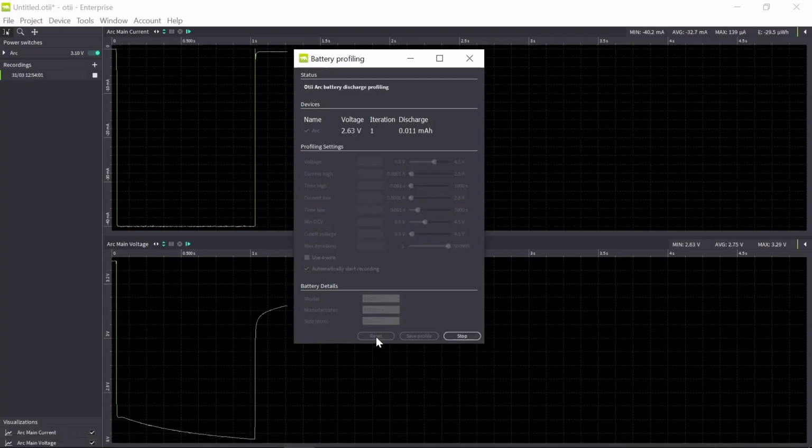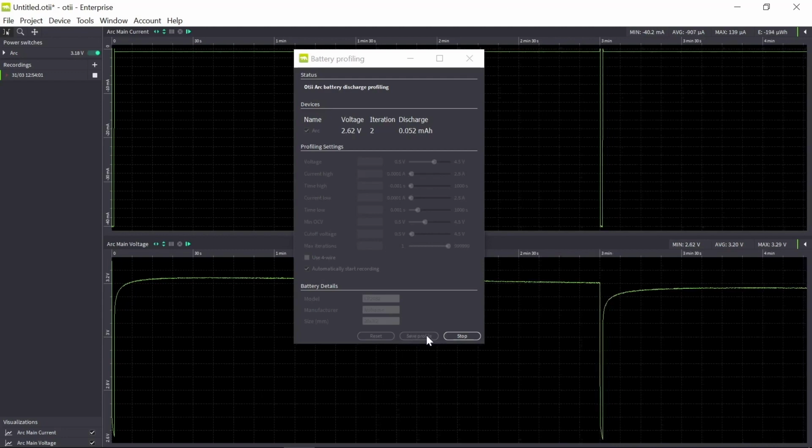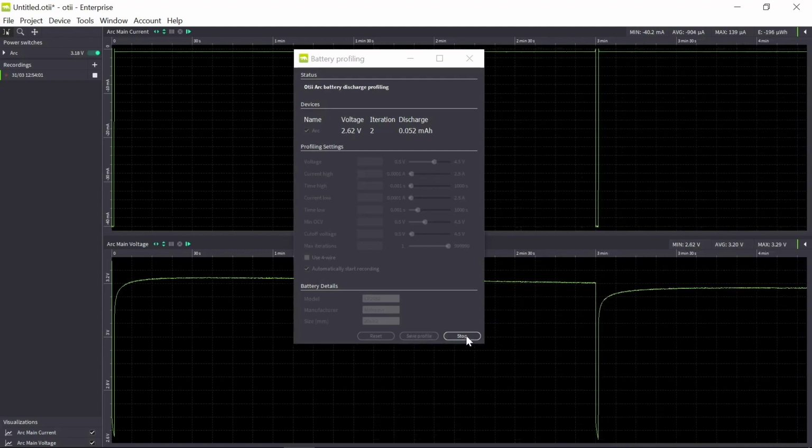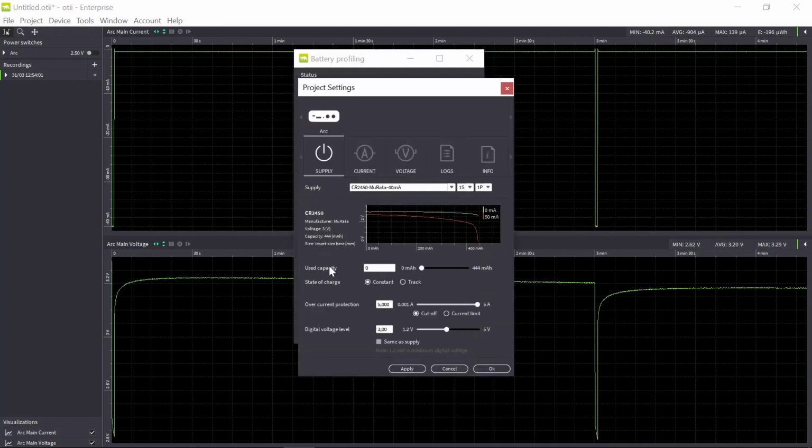This way you will gain a realistic insight whether these batteries have the capacity and the right behavior to support a number of scenarios that your device will be in. And yes, you need to do this for the normal usage and for as many scenarios you believe are relevant. If it is relevant for your use case, also profile these in different temperatures, since battery performance is very dependent on that. You can use the more realistic battery capacity from the profiling in the OTI battery life estimator, since you should continue to estimate battery life for every change made during the development.